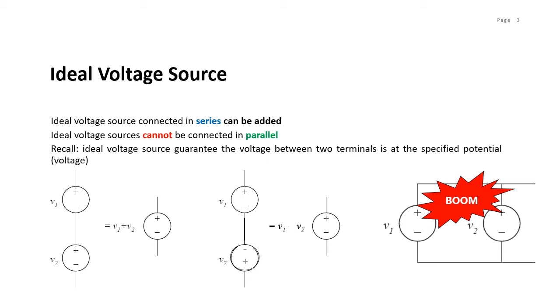While it may not be the best practice for circuit analysis, ideal voltage sources can be connected in parallel provided they are of the same voltage value. Therefore, connecting together ideal voltage sources that have different voltage values is not allowed. And being short-circuited by an external closed loop or branch is also not allowed.